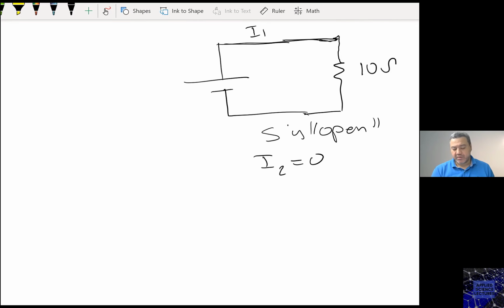I know this one is 10 ohm. The whole branch with the switch open would now be completely removed. It will be useless. It will not contribute to anything. Okay, so the question is asking, find the current when the switch is open, and then when the switch was open, the current was 4 ampere. Now let me draw the circuit when the switch is closed.